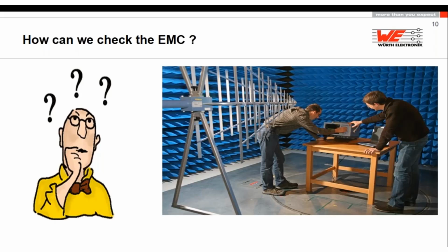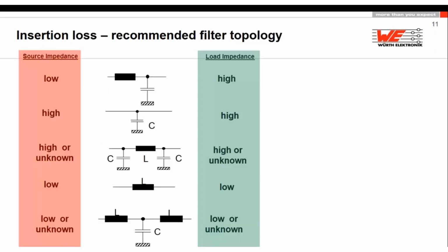I would suggest buying a spectrum analyzer, and having some near field probes for electrical field and for magnetic field, and then you can start to investigate and find out where the EMC noise sources are and then fix them, and then go just for qualifying in the EMC lab.